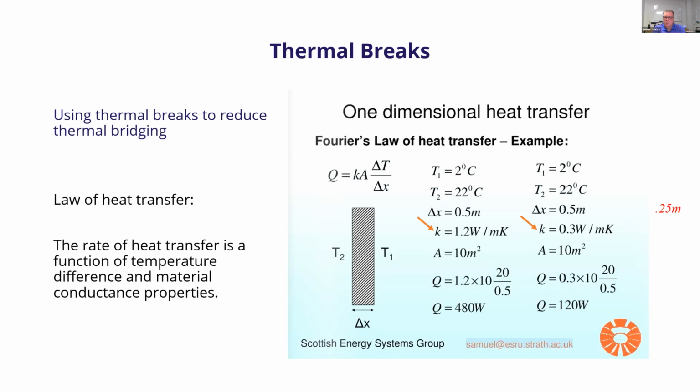What happens if we change the thickness though? If we take half the thickness, what happens to the heat flow? The heat flow doubles, okay? So that's how those are related. What happens if we change the temperature difference to 10 instead of 20? The heat flow is reduced by half, right?